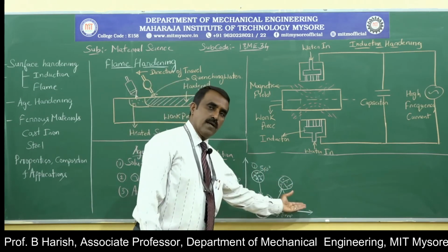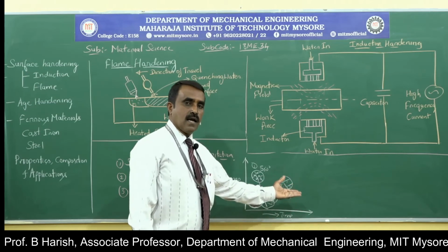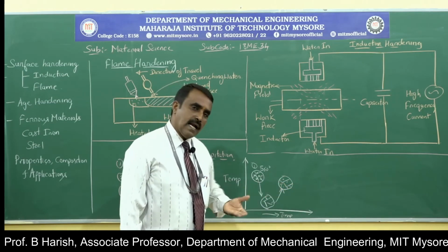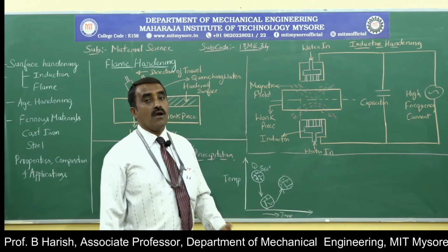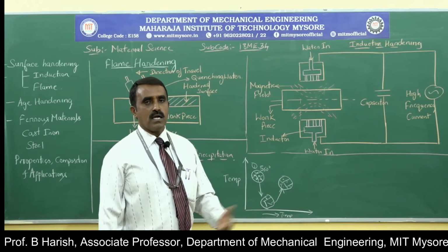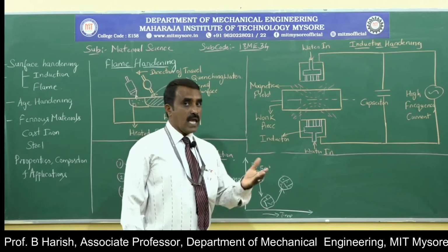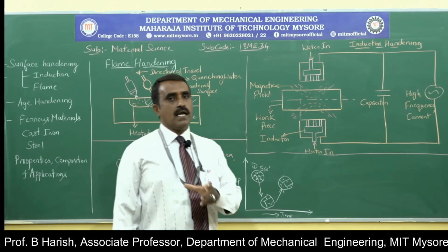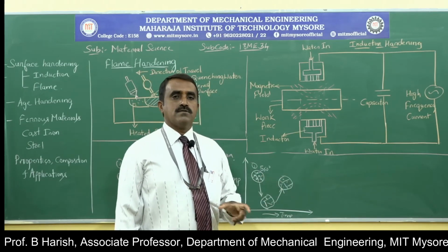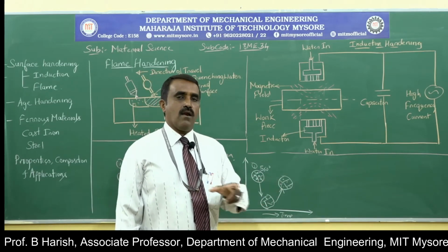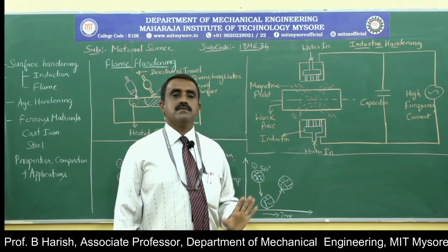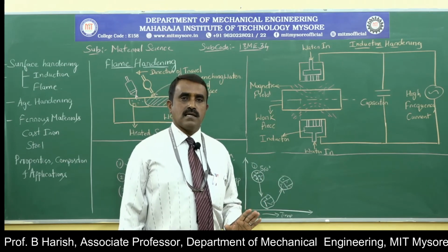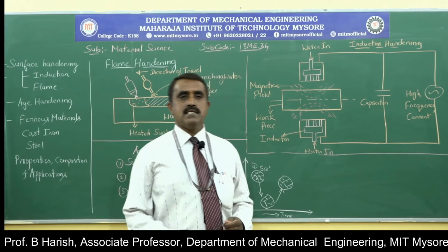It may be at the same temperature, or it may rise to a very low temperature and be kept at that temperature for a longer duration of time. The longer duration is very important. Age hardening takes a lot of time. When it is kept at that temperature for a very long period, its hardness increases. That's about age hardening.